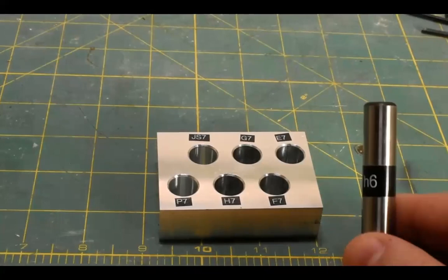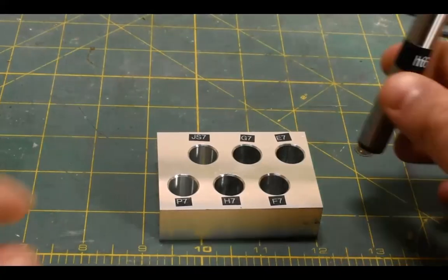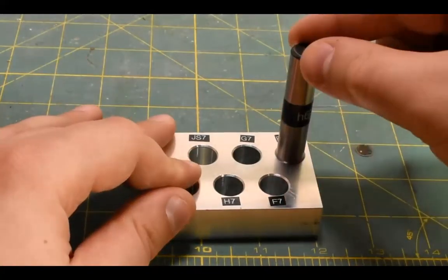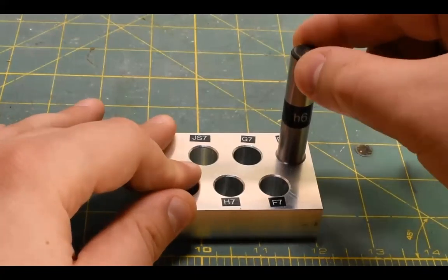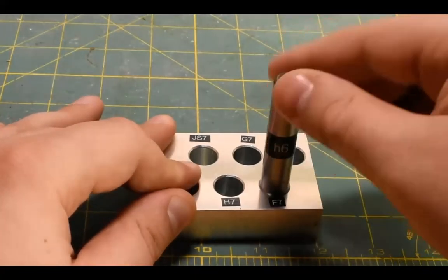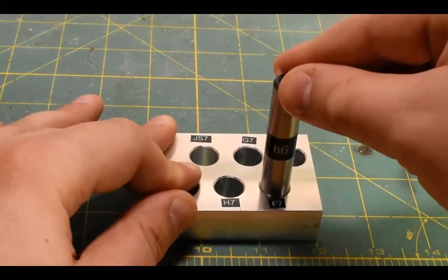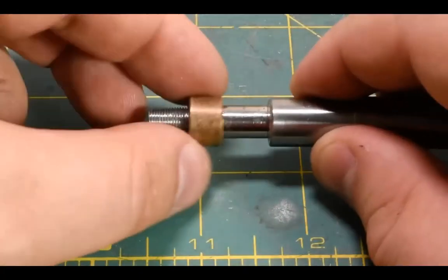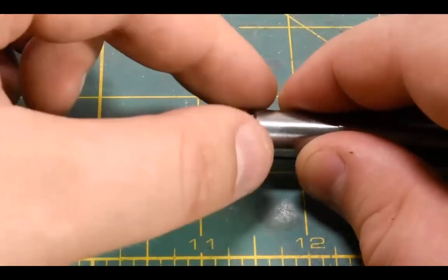For a given fit, we will usually have one component driving the other one's required tolerance zone. In this example, where we bought the dowel pins, we have no input on their tolerance, so it was a shaft basis fit. If we're designing a shaft that has to fit in a purchased bushing, we can't control the tolerance of the bushing, so we have a hole basis fit.